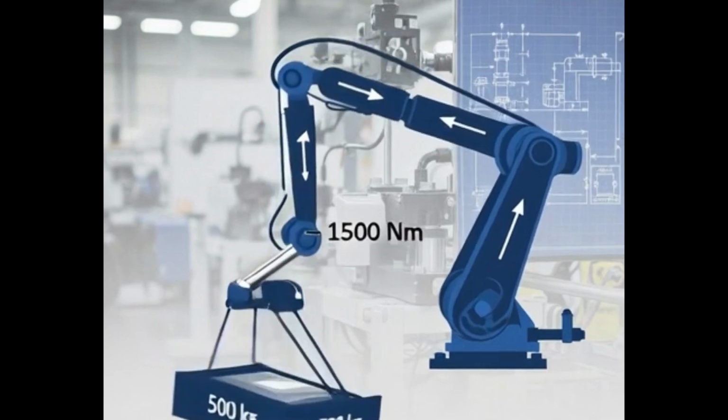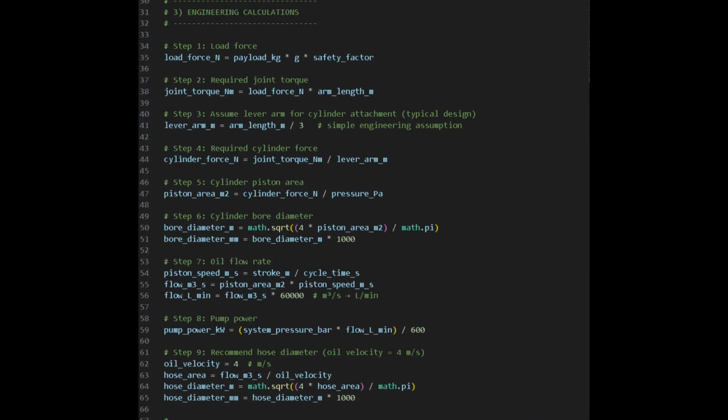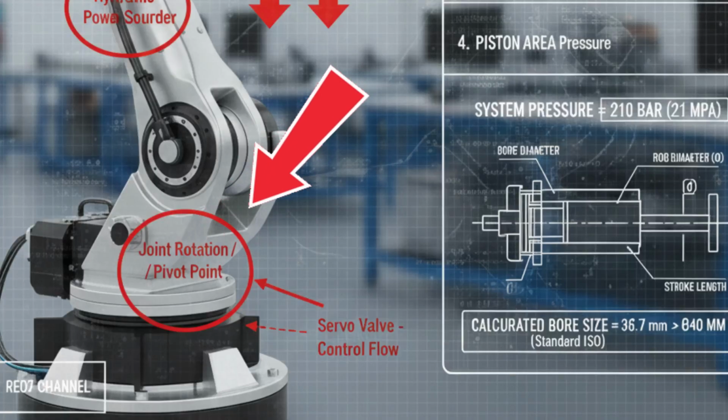Step 1. Calculating load force. First, we calculate the load force created by the payload. In physics, force equals mass multiplied by gravity. So in Python, we calculate load force equals payload times gravity times safety factor. Gravity equals 9.81 meters per square second. We multiply by the safety factor to ensure safe operation. This gives us the real force the joint must handle.